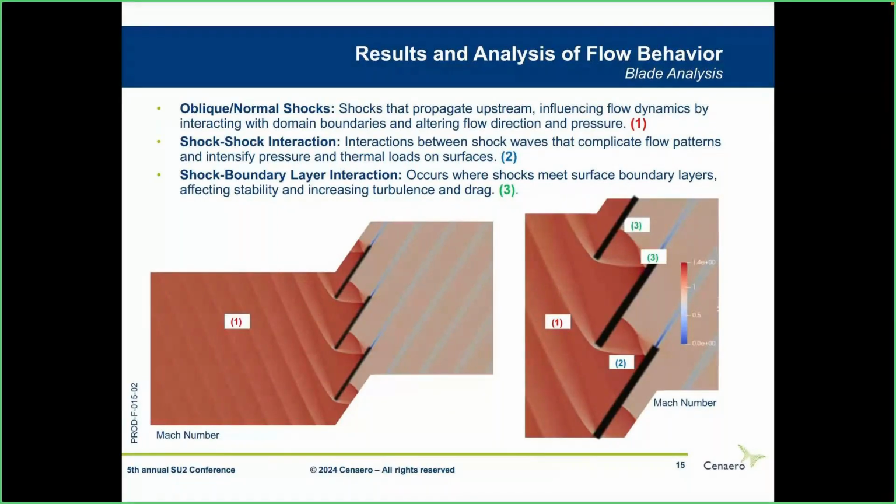I was not able to use the non-reflective boundary condition when working with a supersonic inlet. I tried Riemann, and I don't remember the other one, but I have a Mach number of 0.99 at the inlet, and here the prescribed Mach number is 1.217. So I cannot have that.